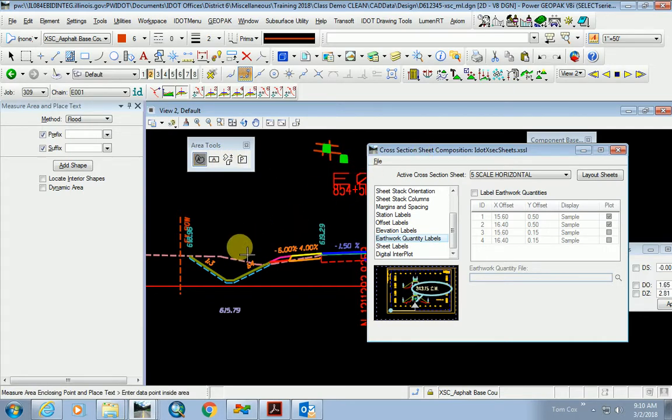And then afterwards, you go through, you got the numbers, you got the cuts and fills, you key in that Excel spreadsheet. From that, you create yourself a schedule, then you send to construction, just like you do with all the other quantities that you calculated in Excel, and you email to construction that Excel spreadsheet that includes all the cuts and fills and how you computed your earthwork quantities and other quantities.